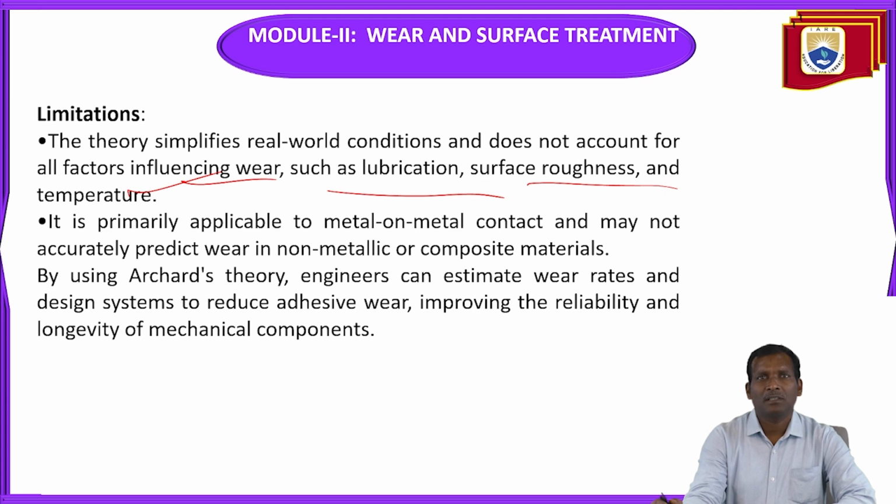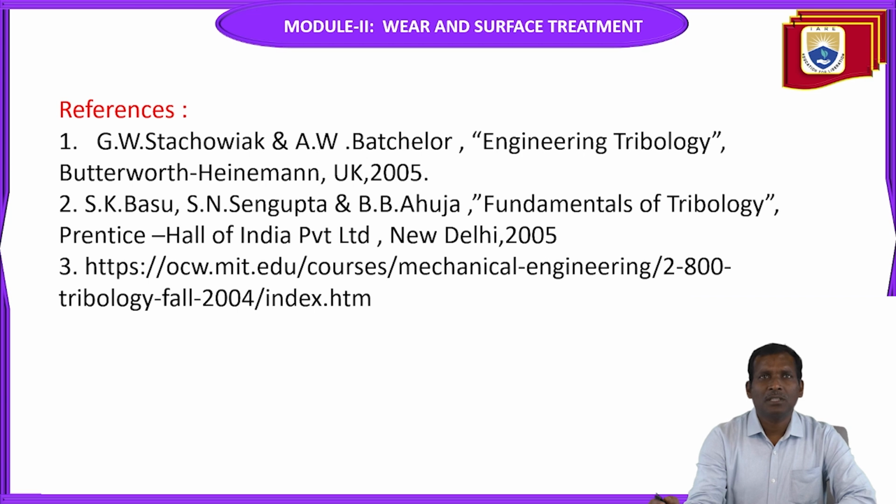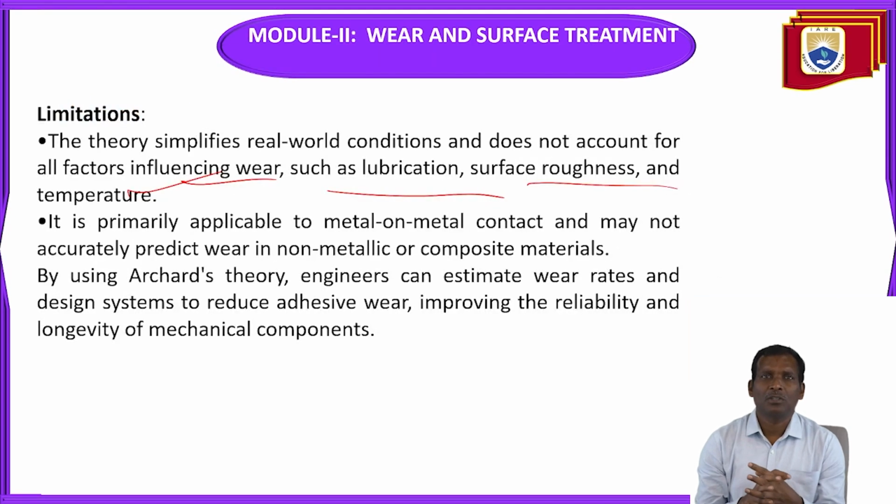By using Archard's theory, engineers can estimate wear rates and design systems to reduce adhesive wear, improving the reliability and longevity of mechanical components. So by using these theories, you can avoid the wear and also improve the life of the components. Every engineer should use these theories to predict the wear before designing components.